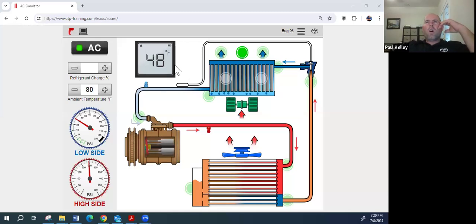If we went out to that car and that other RAV4 blew at 39 degrees and theirs is blowing at 48, now we got to look a little further, right? So this could have been an NPF. But the problem is we went and verified it and we're like, you know what? The other one's blowing 9-10 degrees cooler. There is a problem with this car.